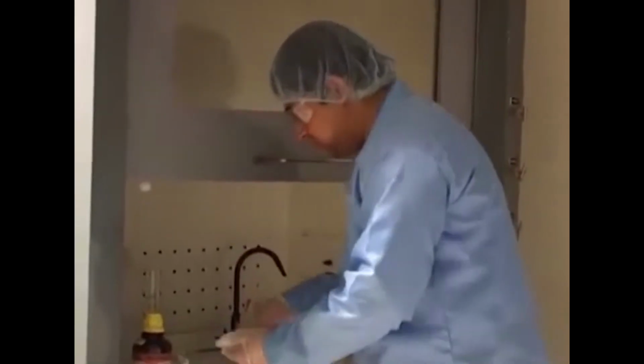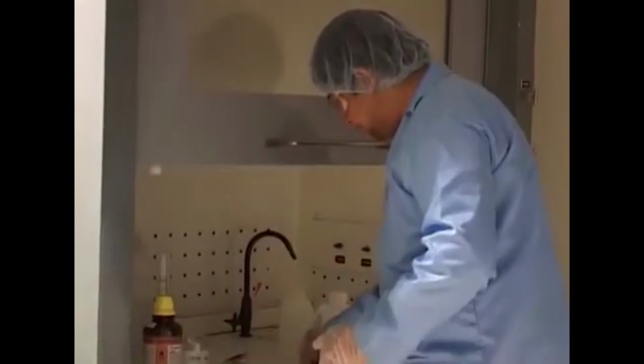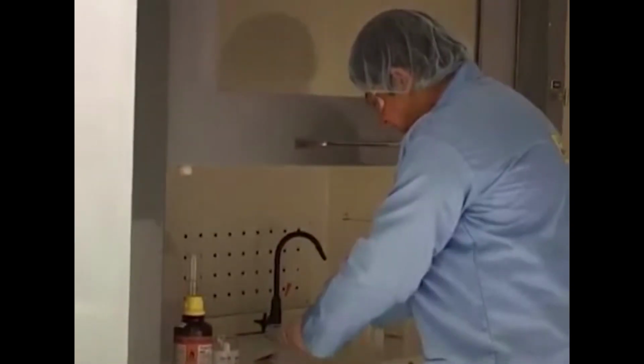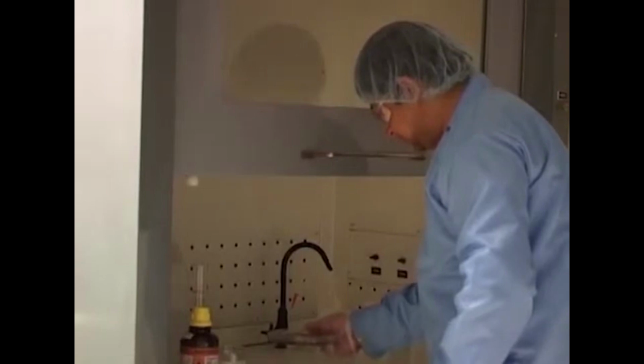This is set to about 4 seconds, and then we keep giving some swirls to this developing action, and you have to ensure that this happens so that you get good features on the surface. As you can see in this case, immediately after you put it into the developer, the features nicely get generated.